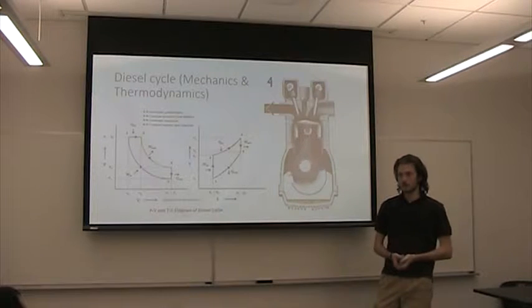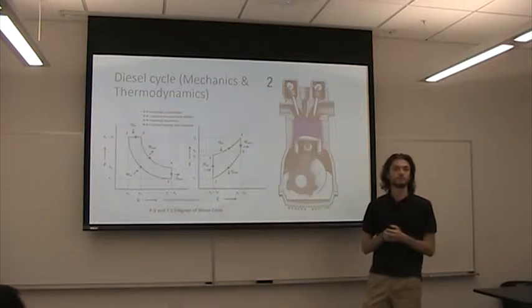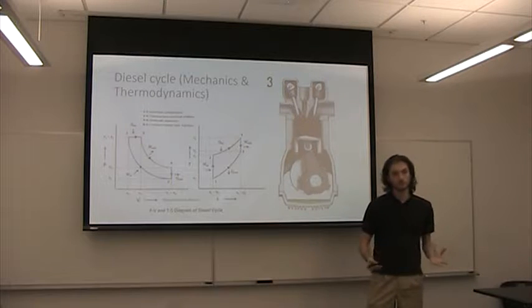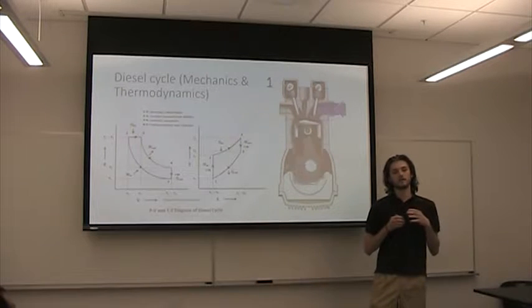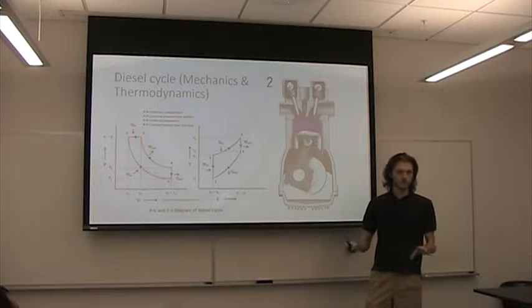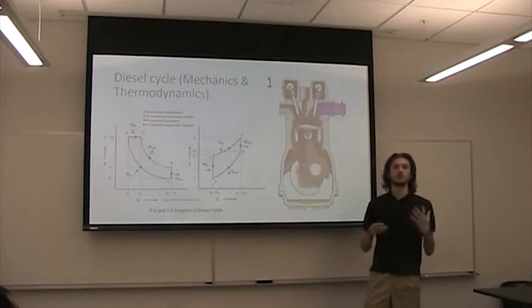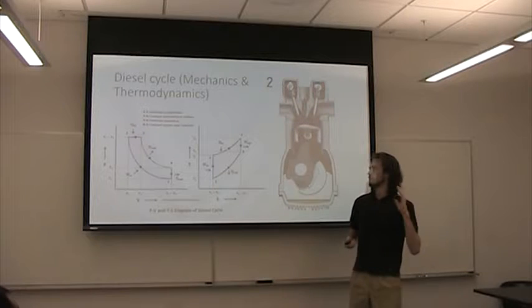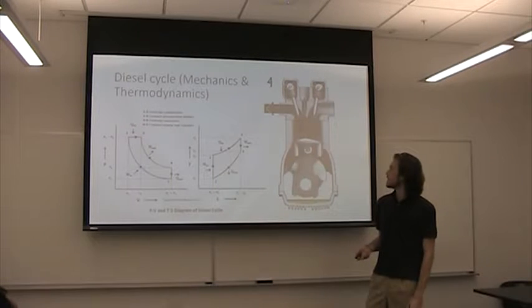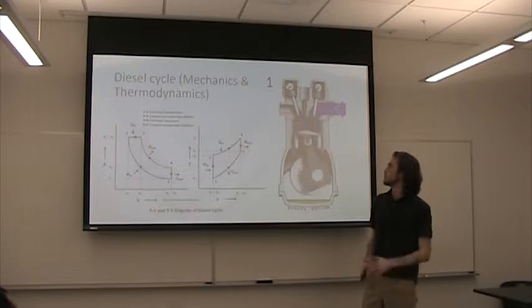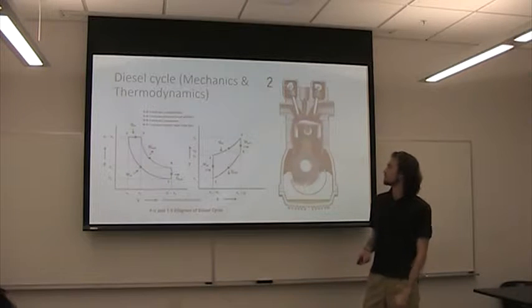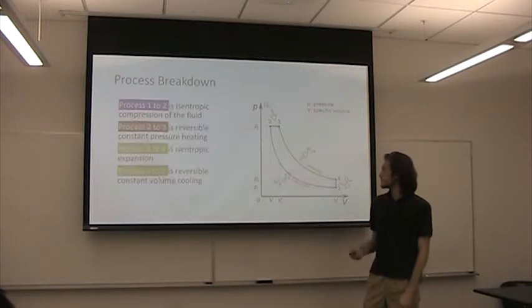As the explosion happens, it pushes the piston back down, which is how you get the power out of each cylinder. Which is why most car engines have at least 4 cylinders, since the whole cycle is 4 strokes and only 1 stroke produces power, so that you can get power at all times. And the last stroke is to eject the emissions.